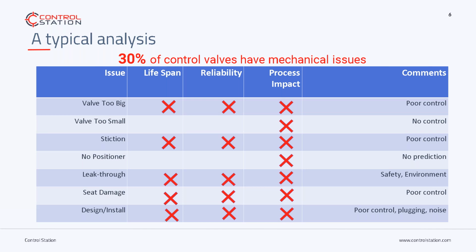If we poll the audience, I would expect less than 5% of your valves would have positioners. They're only really put on critical valves.